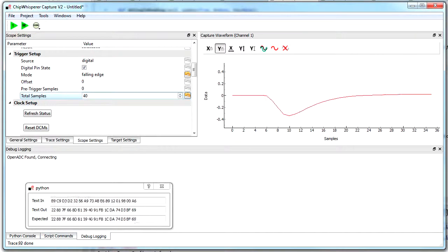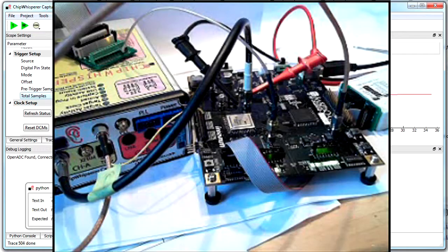So that's using the clock output of the ChipWhisperer for playing with some more interesting things on the FPGA, running very high speed AES instead of more standard. At 150 megahertz, also, we're running beyond the official sample rate of the ADC, so you may start to get into some issues here. Like many things, you can actually push it well beyond the specs, but hope you found this somewhat interesting. Thanks for watching.